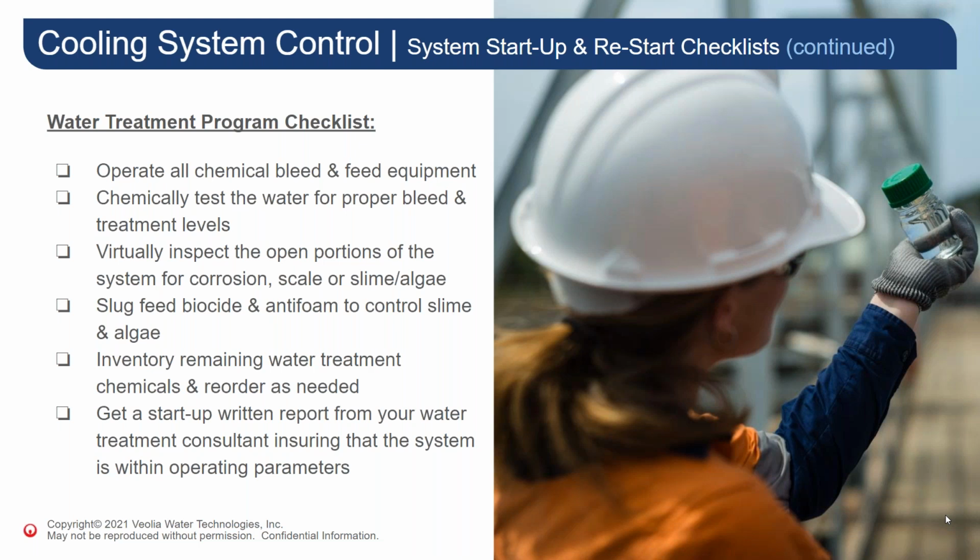This is also a perfect time for a good disinfection of the cooling system to kill existing microbial organisms, especially Legionella and other harmful bacteria. Lastly, it's also an excellent time for system-specific operator training, especially concerning Legionella exposure risk minimization for your employees.